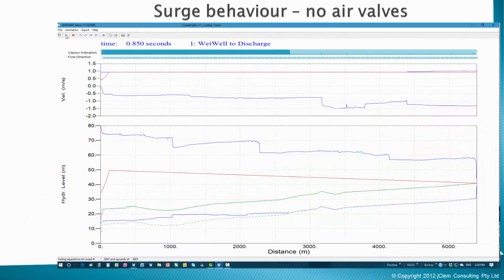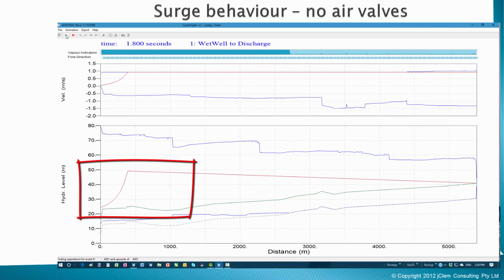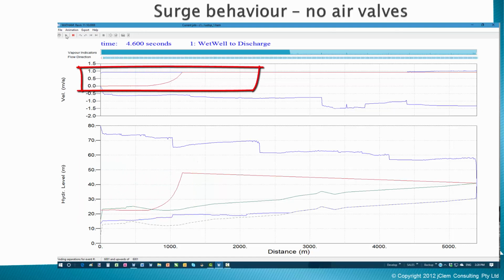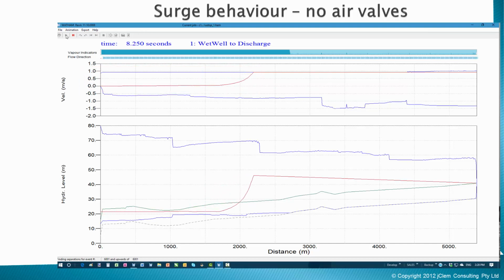The pump turns off. We see a strong downsurge in pressure travel up the pipe, large enough to create negative heads in the pipeline. Note the top velocity graph. Note that after the pressure wave has passed a point in the pipeline, the fluid velocity is dropping to 0. And this pattern continues until almost 12 seconds have elapsed in the simulation.